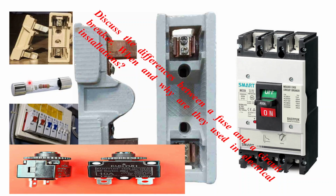Fuses are typically one-time use devices and need to be replaced after they have operated. They have relatively simple construction and operate based on the principle of thermal protection. Fuses are available in various types, including fast-acting, slow-blow, and current-limiting fuses, each designed for specific applications and current ratings. So, what are the applications of the fuse?